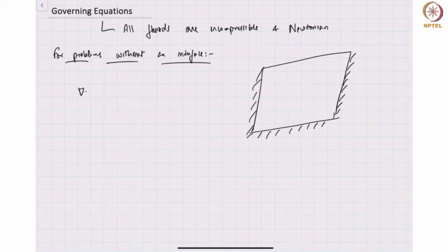So let's start by writing down the continuity equation. That's the mass balance equation, and the momentum balance equation would be density times the total derivative or the substantial derivative, equals the pressure gradient term, plus the viscous term. Now you could in principle have other forces at play. For example, if this is a heat transfer problem, then you will have an additional body force term because of changes in density because of temperature, and you'll also have a temperature equation. But we are ignoring all those complexities in this course.